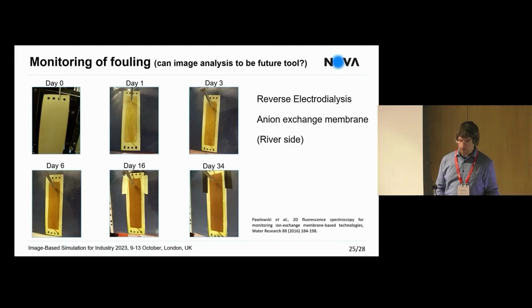To finish, the main problem of membrane processes is fouling. Because when we treat water, it has organic compounds, colloids, clay. So basically, the channels of membrane processes may clog.